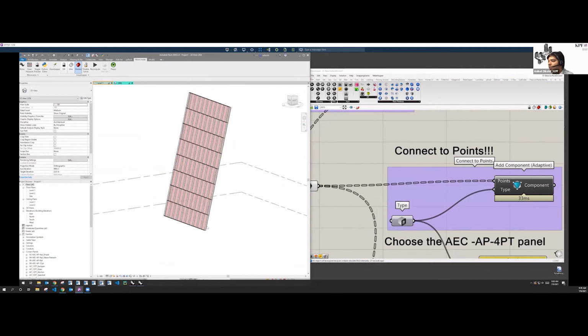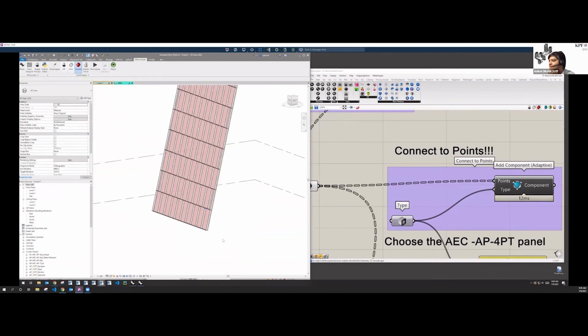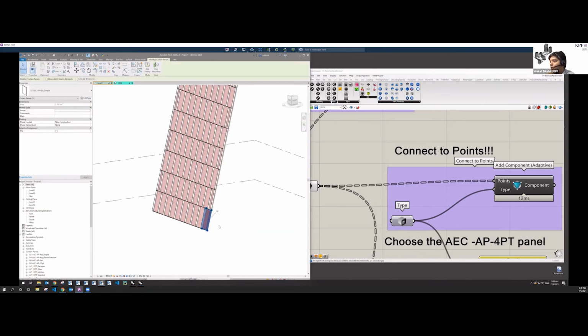One of the cool things that I've noticed inside of Rhino.Inside is that, until the object or the element that you're creating inside of Rhino.Inside is unpinned, this is only valid for the same session. Rhino.Inside does not do element binding, so if you do something, close out and then reopen the Grasshopper file, it's not going to remember that.